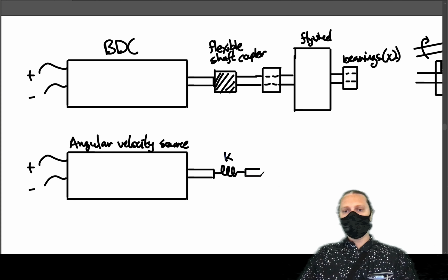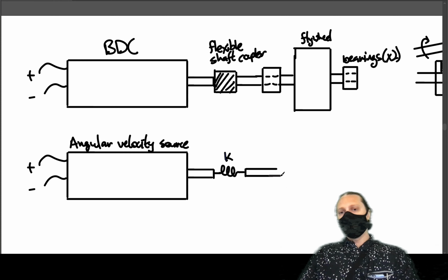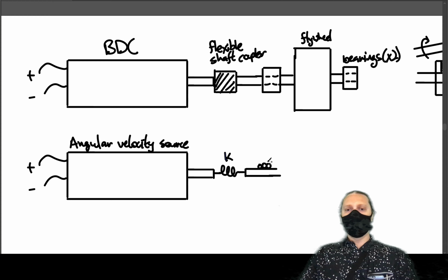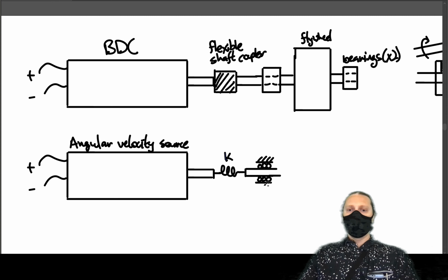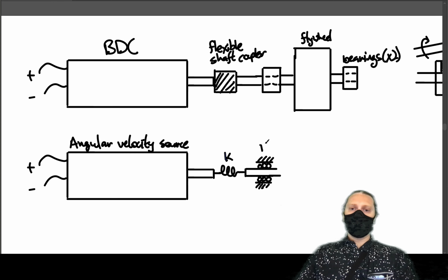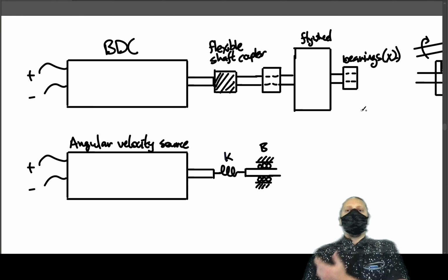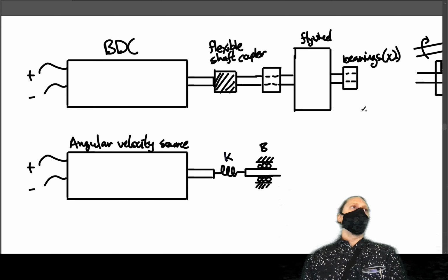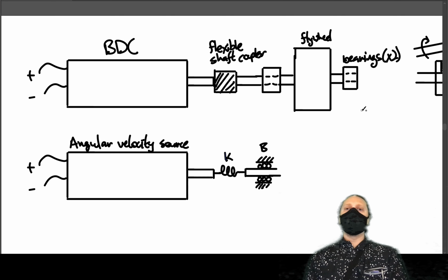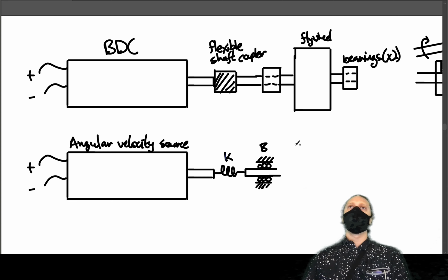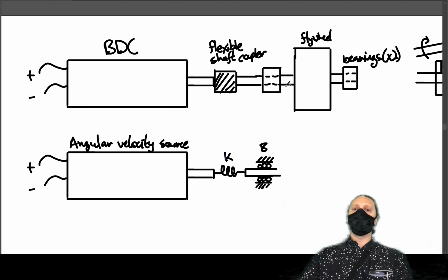So this shaft is going to go through a bearing damper, which we typically denote in this sort of schematic form like this. And there are 2 bearings here. There's a bearing on this side, there's a bearing on this side. Assuming they're the same bearing, why should we probably just lump these 2 bearings into one bearing element? The primary reason is that they share the same angular velocity.